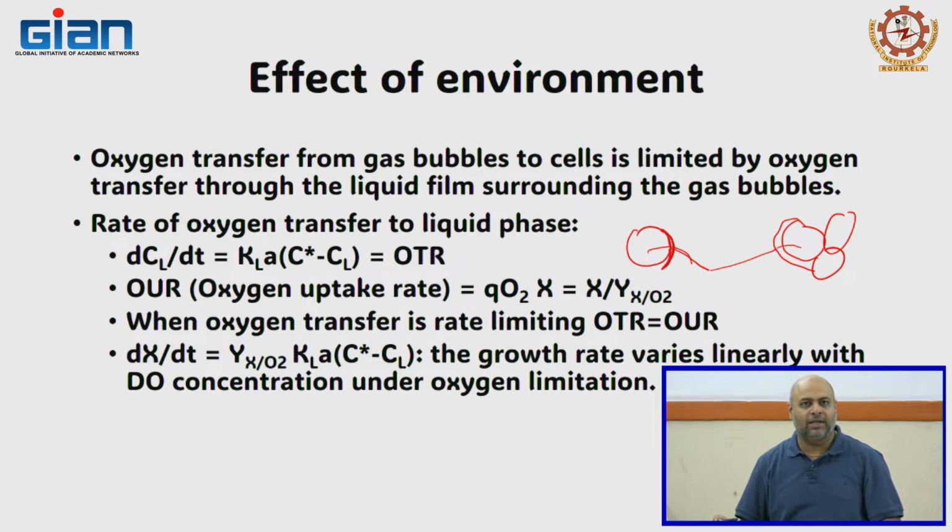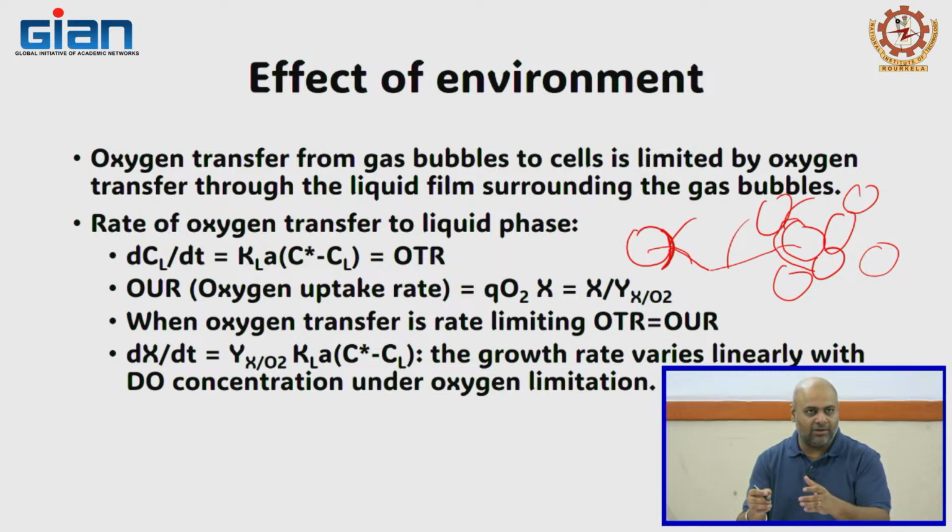So it becomes like you have mass transfer through multiple mediums with different diffusivities. So the diffusivity here is different, the diffusivity here is different, the diffusivity here would be different. It's like series resistances which will get accumulated, so it changes. Now if the sparger was working properly, there would be gas bubbles around the cell biomass, so the transport might be direct, so that will improve the overall oxygen transport.